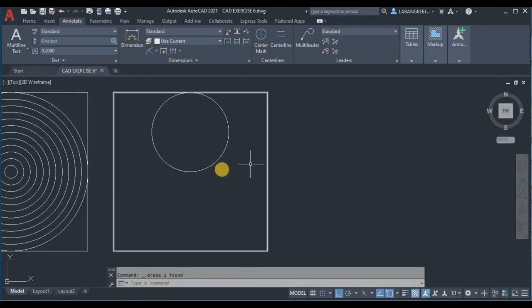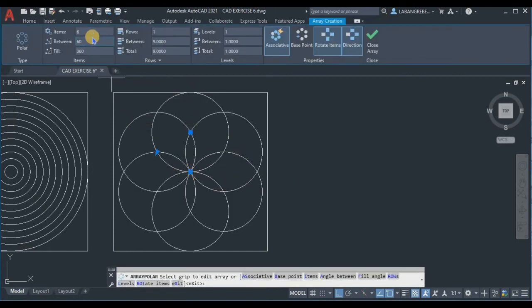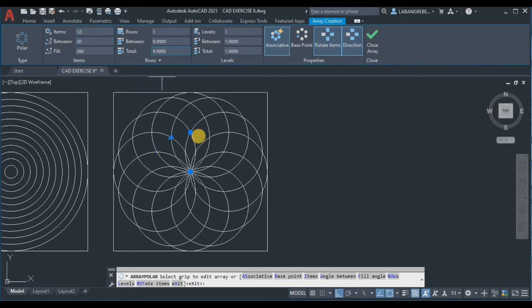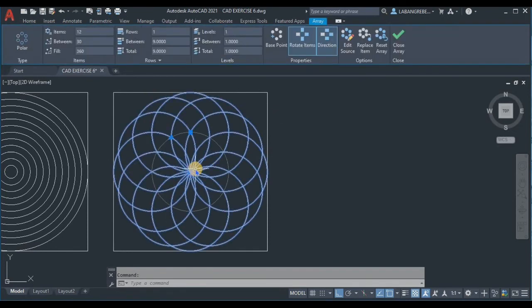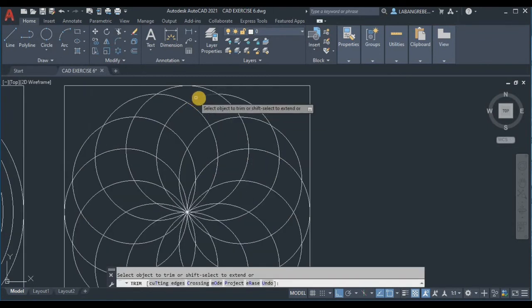And then after that, we're going to select this circle, and we're going to use the array, the polar array, and then click this polar array, and then click the object, specify the object in here, and then let's gonna have the items is actually 12, and then let's gonna close, and then explode this line, X, and then enter. Then using this line, we're just gonna have to trim all the excess arcs. Double enter if we were going to have it here. Trim this line, trim.